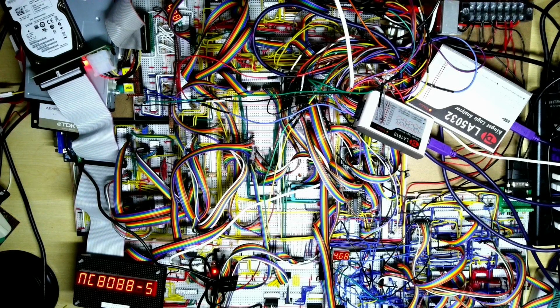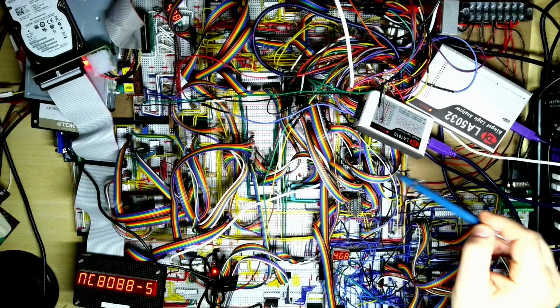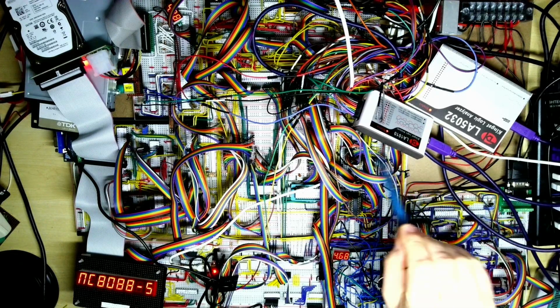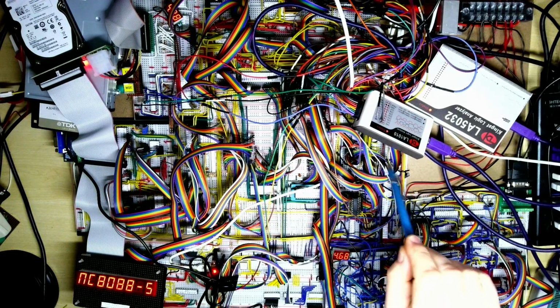What I do have plans to do in the next project is to make using the logic analyzer a lot simpler. So down here we've got our Intel 8088 CPU, and this is a 16-bit CPU, but it talks to the outside world through 8 bits, and you can just about see the 8 data bus bits there. We've then got the system clocks underneath here, so the main system clock and a lot of the timing and reset circuitry underneath here.